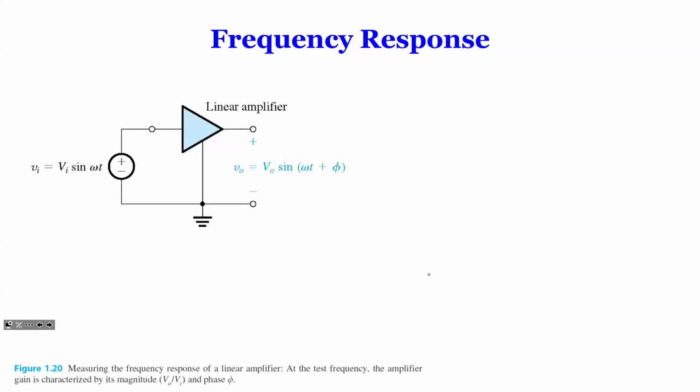That's a ratio. We can have a couple of examples to see the difference between a linear and a nonlinear amplifier. Say this is the input, and this is the output. From here to here, you're only amplifying the magnitude, the frequency doesn't change. So this is called a linear amplifier.